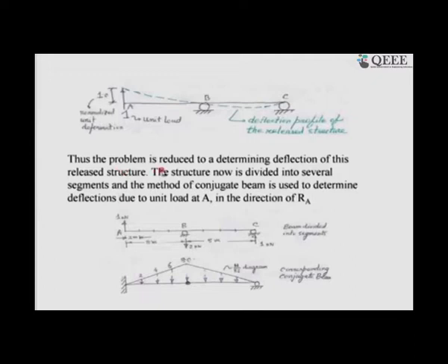The problem is that we have avoided the real issue which we were having at the first principle, that let the unit load move, I draw the rigid free body, and from there the solution for the different stress resultants. Those we are not doing. We are already with the Muller-Breslau principle. We have got the qualitative shape of the diagram. Now, it is left to us to determine the quantitative values, and the problem is reduced to determining the deflections of this released structure.